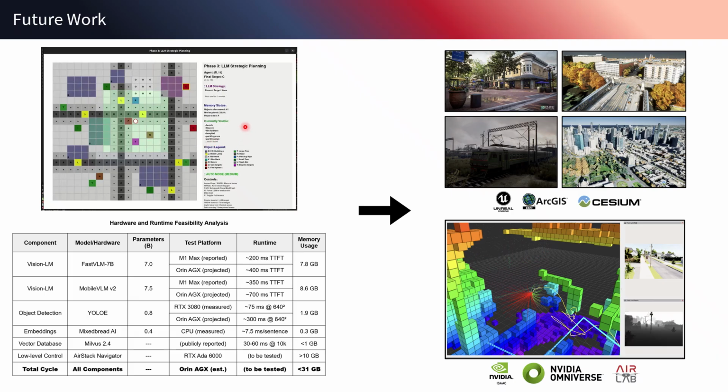And then we would also have long-term memory. The idea actually came out as a consequence of one of the protocols, where we realized that not always do you have some clues inside, right? So you need to be able to switch back and forth. That's why we included vision properly, in the sense that our vision would also work as exploration mapping. So we would be switching between simplified frontier-based exploration and object navigation, and object navigation would use objects as possible clues towards our final target, right?